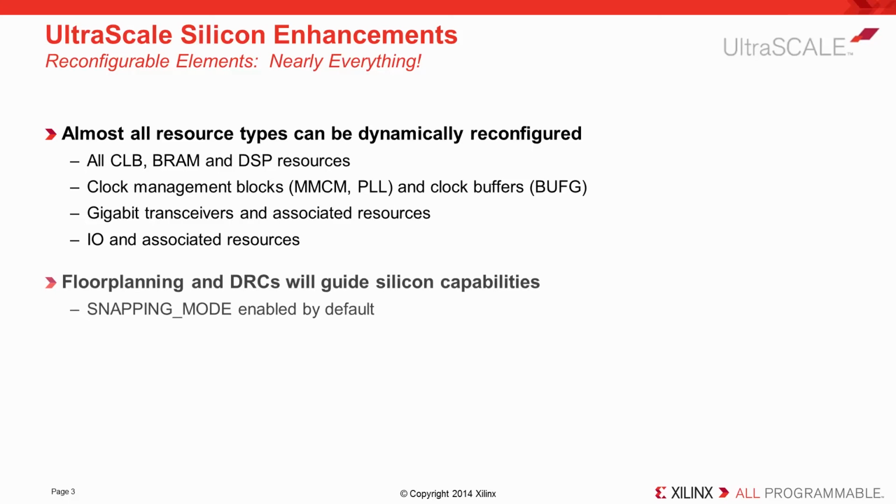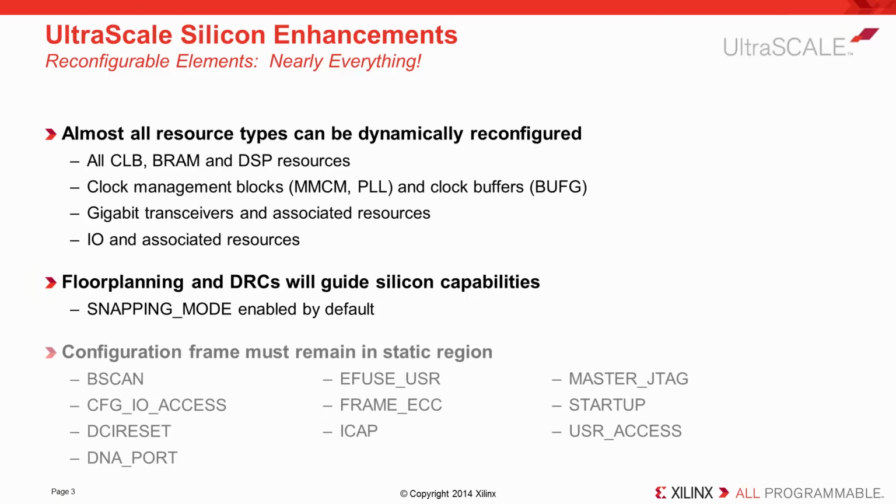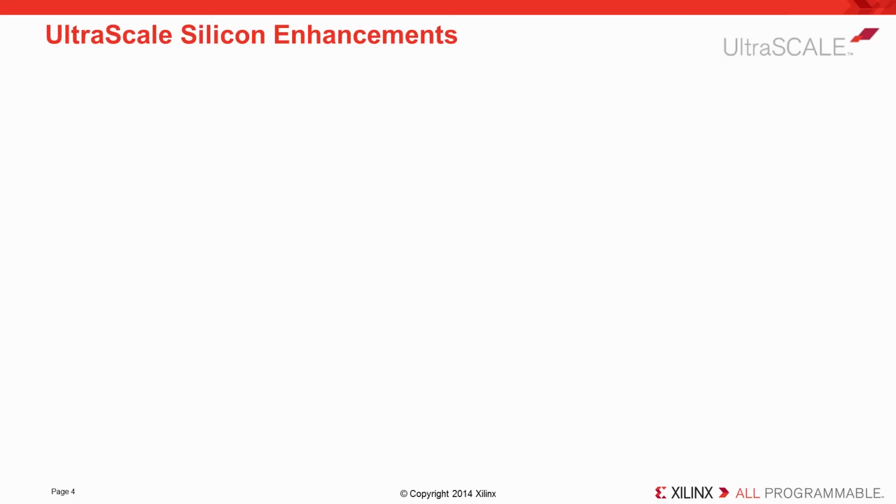Design rule checks help guide designers to create appropriate floor plans to meet silicon requirements. The snapping mode feature automatically adjusts P-block ranges to match legal boundaries and is turned on by default. The only resources that cannot be partially reconfigured in UltraScale are those special components found in the configuration frame. Elements such as boundary scan, the internal configuration access port, and the startup block must remain in the static portion of your design. But wait, there's more.